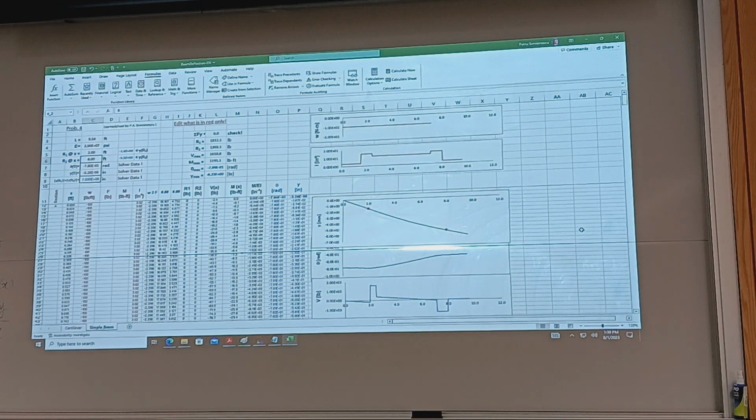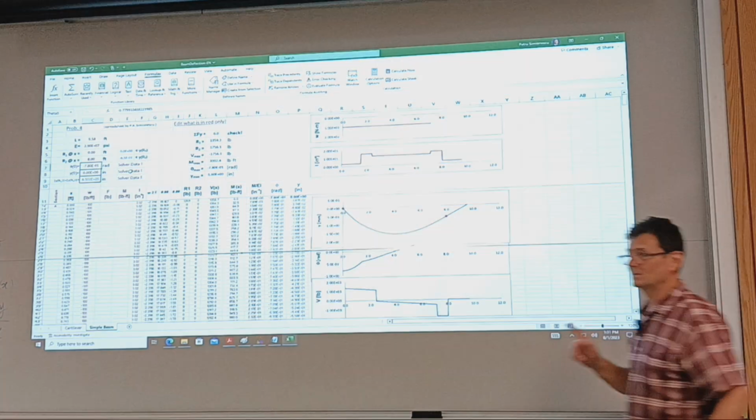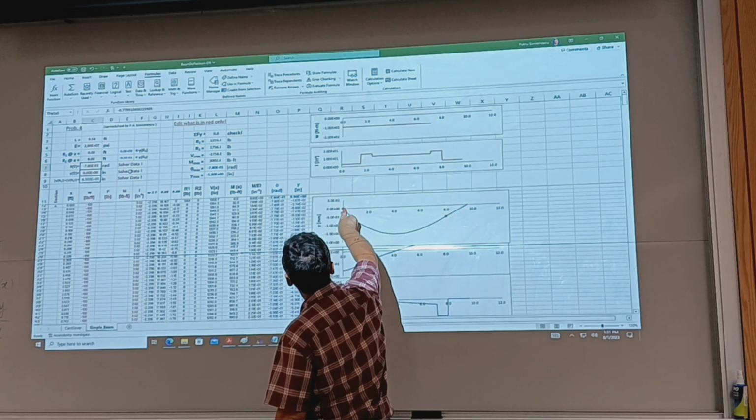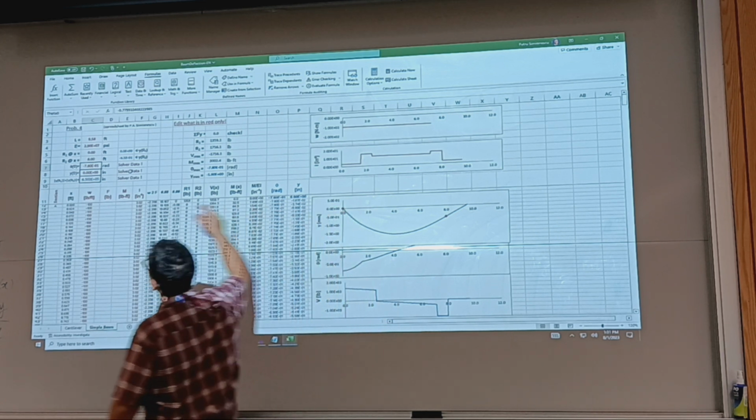There is the solver. I mean, we can try. If I go back to the original configuration, that will make it a little bit easier. So I said this is 0. Okay, this makes it easier. So y at 0 is already, I can make it 0. And then I can play with the initial slope by hand. So you can adjust the value by hand when, in this particular case, the first support coincides with the left end of the beam. Otherwise, you need to play with both.